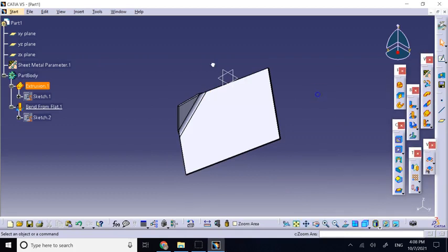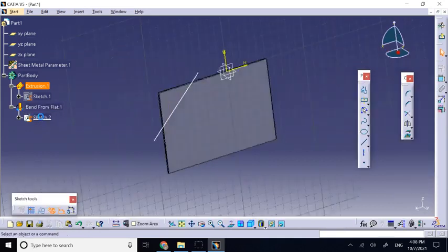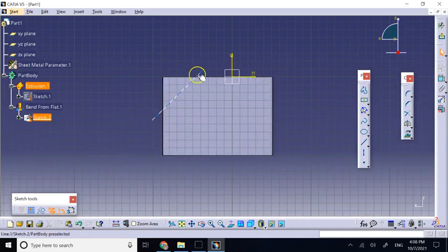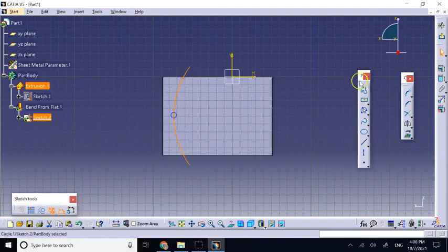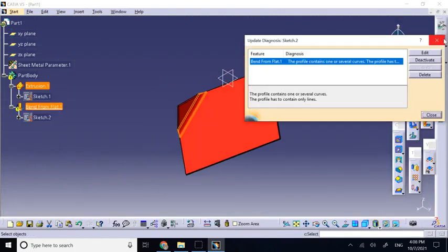Now you might ask this question: here you bend it over a line. Can I bend it on a sketch other than the line? And the answer is not really, unless it's a combination of lines. So if instead of this one I make it like a 3-point arc, something like this, correct? Say, hey, try to bend it over this arc, it is not going to be happy.